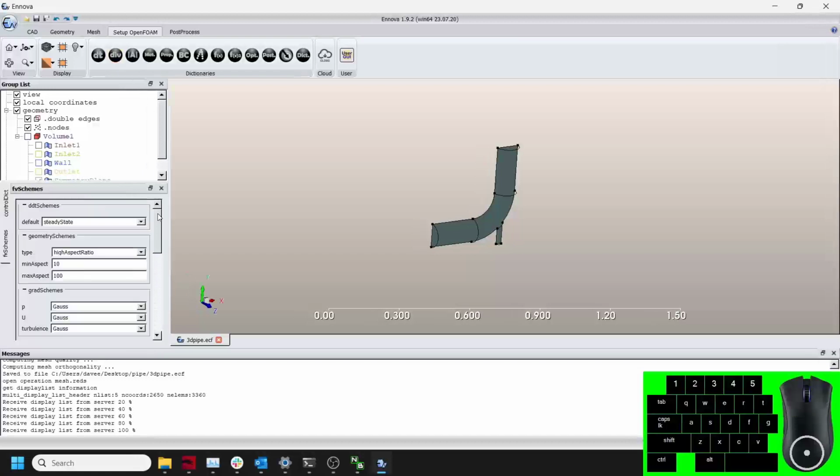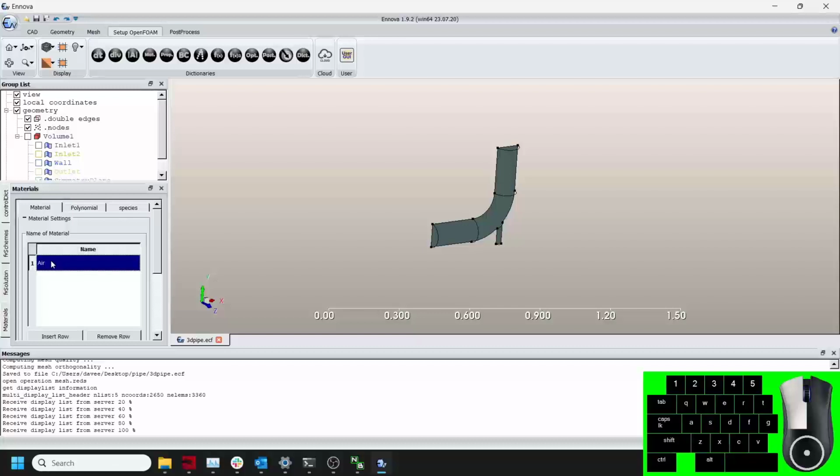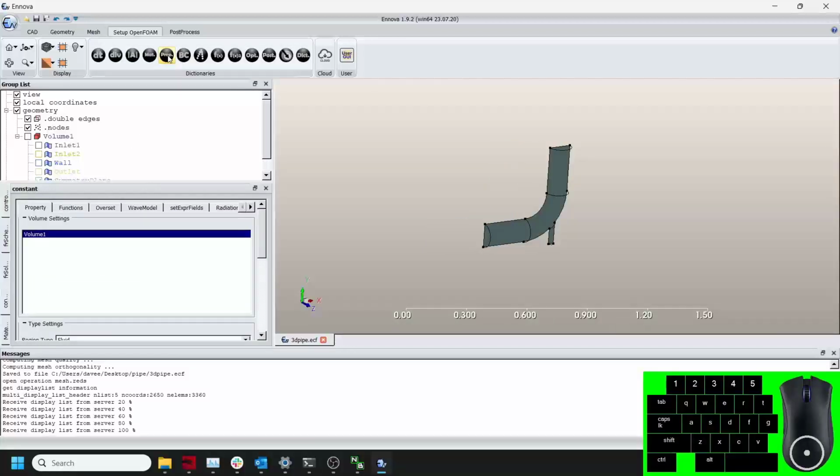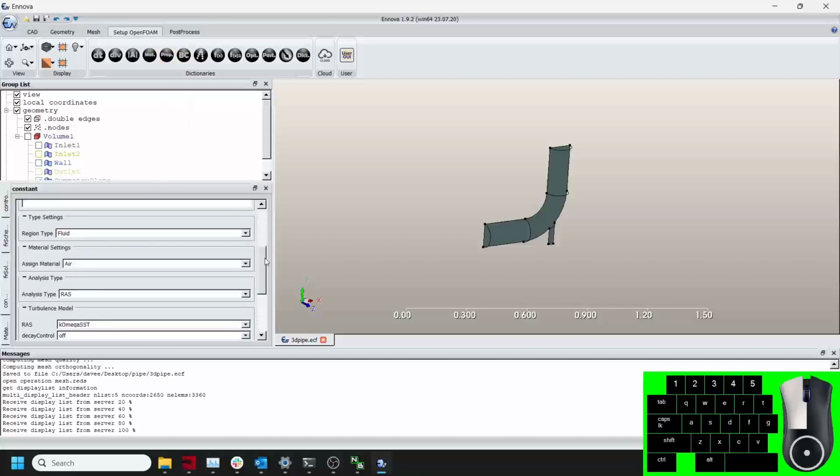We will accept the defaults. We have chosen so far a parallel, steady-state incompressible turbulent solution using RANS. We also now must instruct OpenFOAM about what fluid is inside our pipe. Here we will choose air as the working fluid.